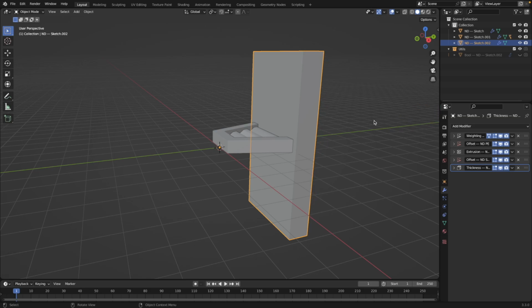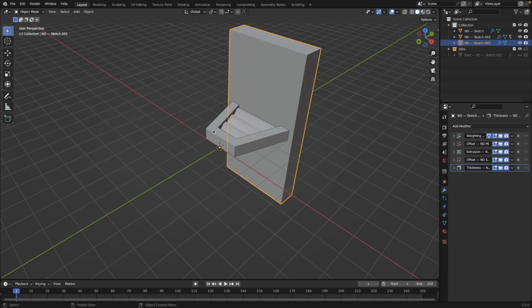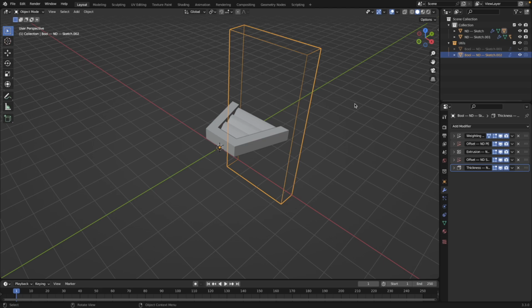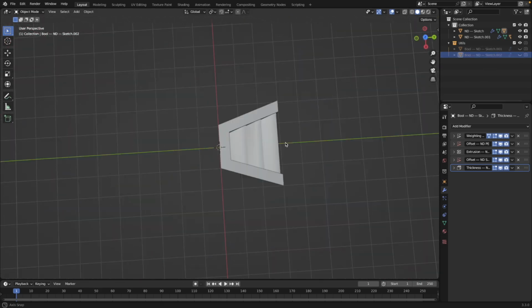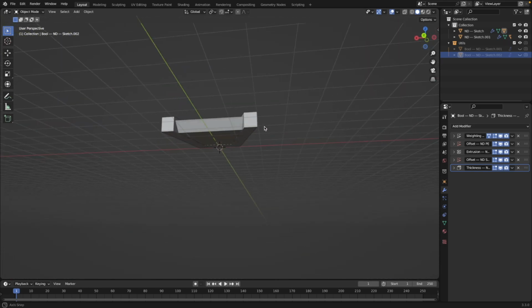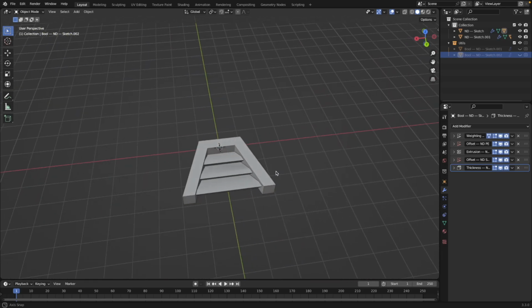So we'll just make it nice and chunky so that it's definitely overlapping the thing that we want to remove. And then we can shift select this outer frame and go into the Booleans and say difference this time, because we're subtracting it away from that. And then again, we'll just hide this wireframe. So now we have that shape. So now we have a flat end here. We have our angled vents that we like. So yeah, that's what I had in mind to fit in that shape.